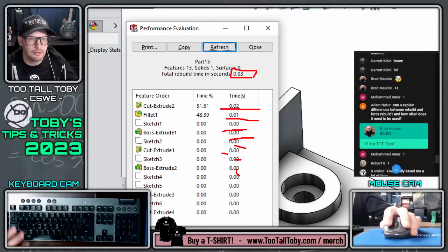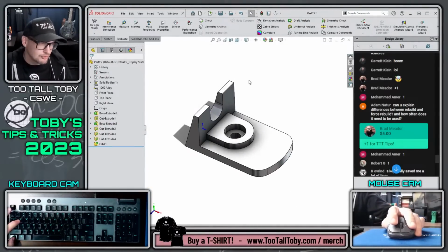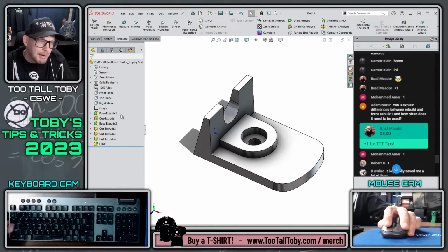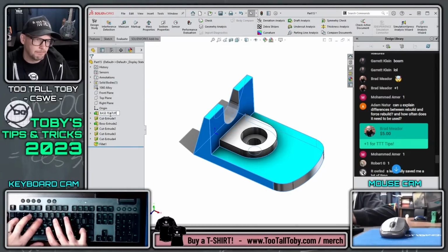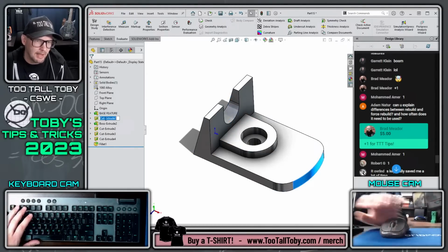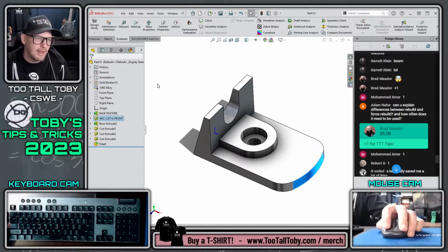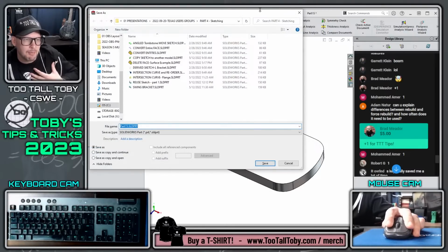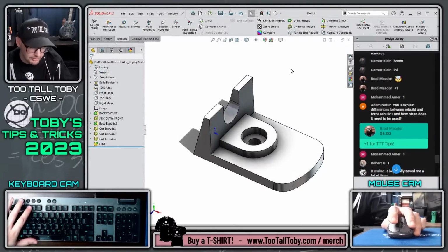Most users, I bet most people in the chat would say, I just use Control Q all the time. My workflow is I rename the tree. So base, feature, cut, arc cut in front, blah, blah, blah. Then I do a Control Q, and then I do a Control S for save. That's how I work through the command. So F2, Control Q, Control S. I just always do a Control Q.